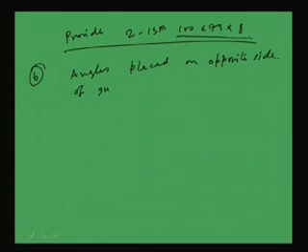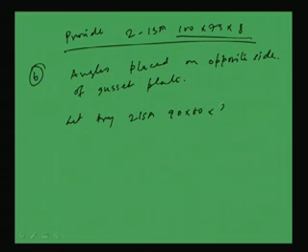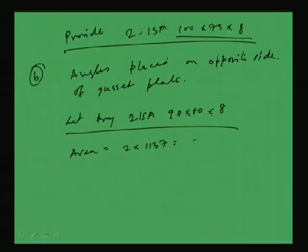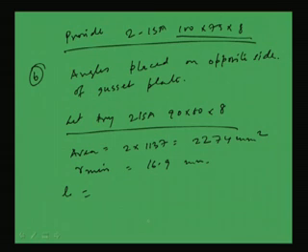Of gusset plate. So, what we will do now? For this case, let us try with the earlier section, say 2 ISA 90 by 60 by 8. Let us see first. The area is becoming 2 into 1137, which is 2274 millimeter square, and r minimum is for this case 16.9, right.